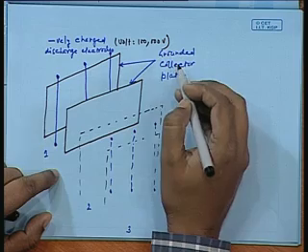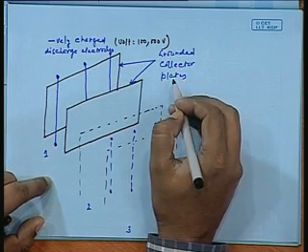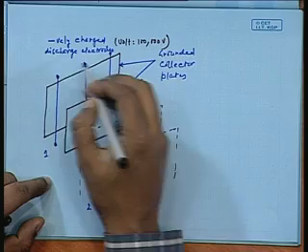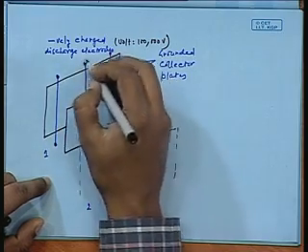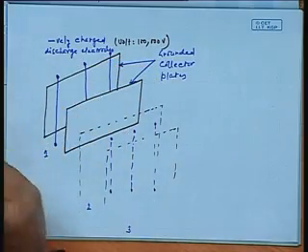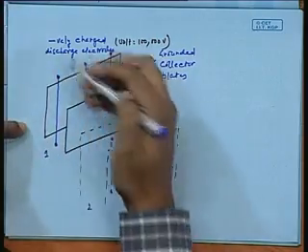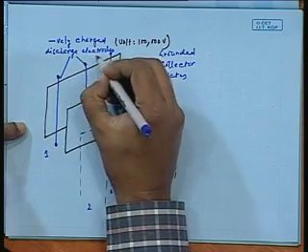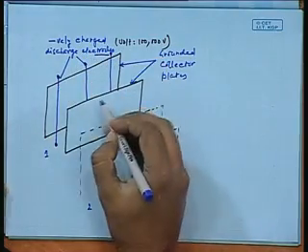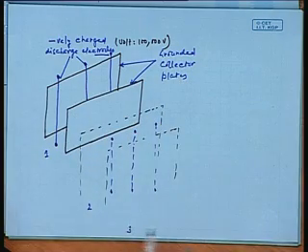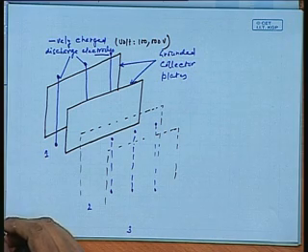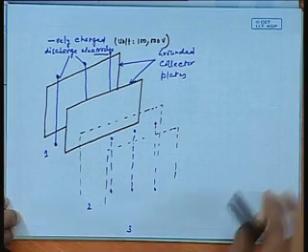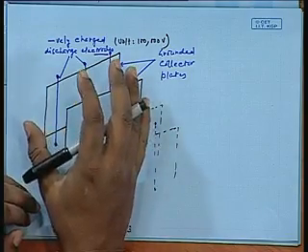This says grounded collector plates. So you have negatively charged discharge electrodes. These are the electrodes that you can see, and these are the grounded copper collector plates. This is just to understand that this is not a single column. There will be multiple columns of this in the electrostatic precipitator.